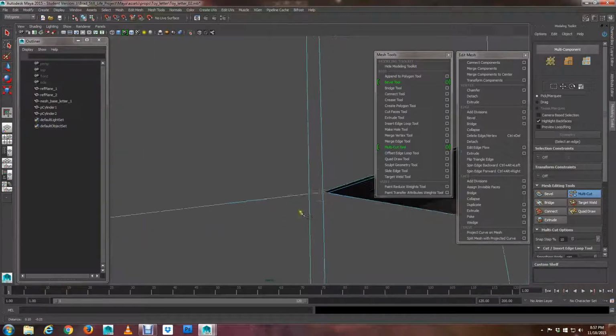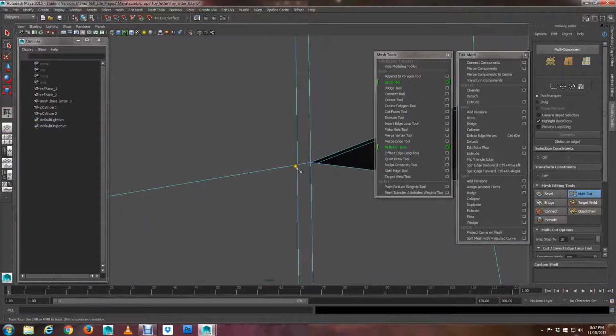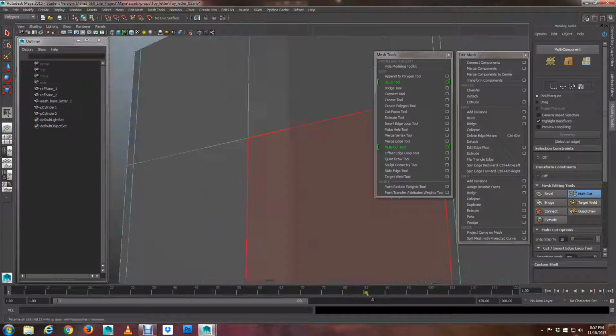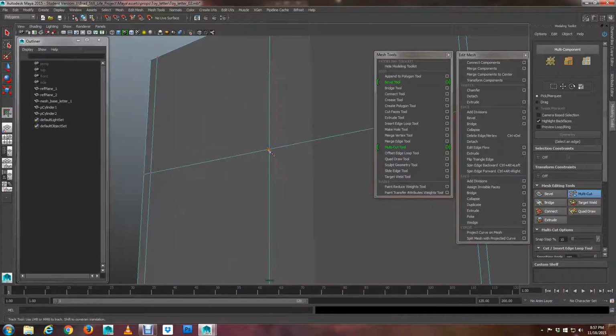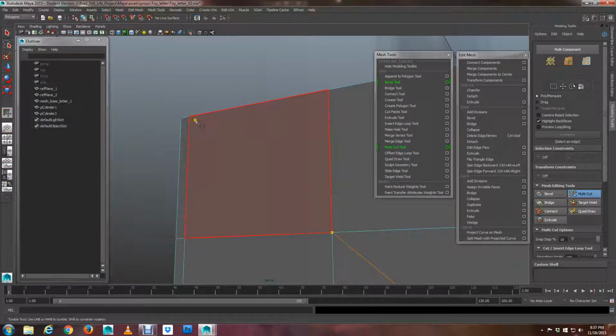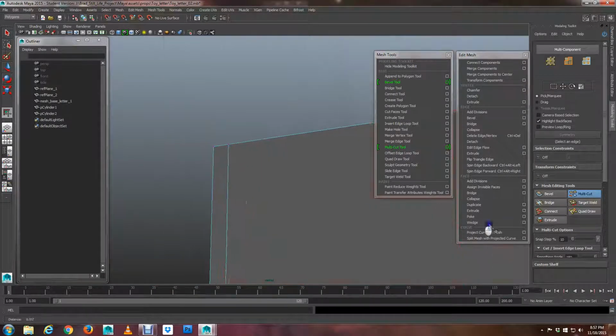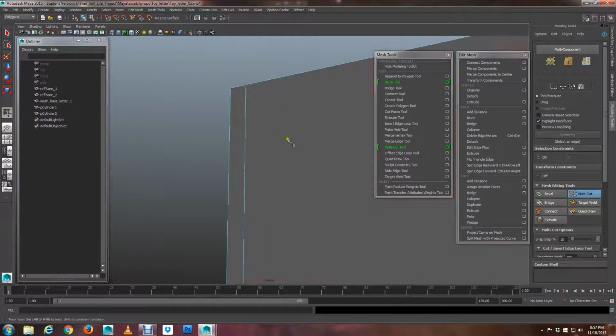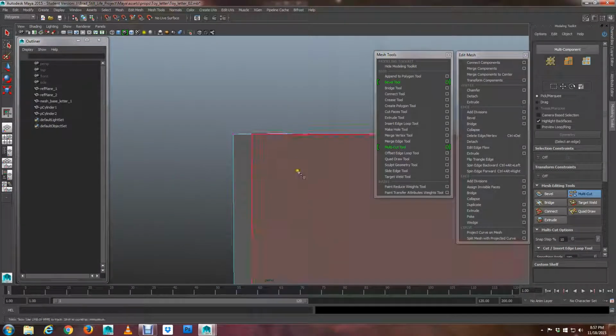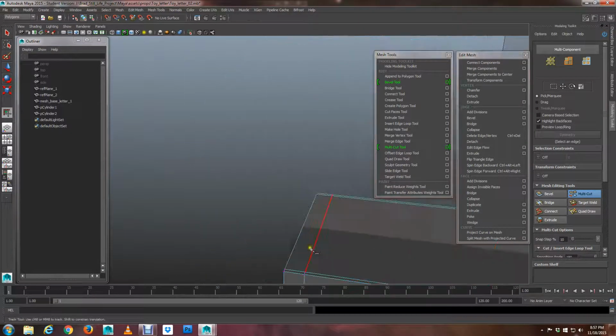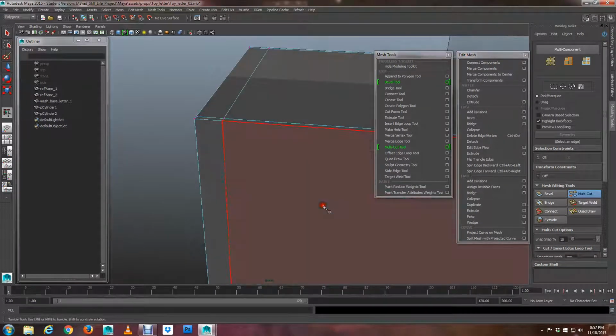And again, when you're making your cuts, zoom in to a point. Okay, so I got this point until it goes red. I click there. I'll zoom out a bit, come up here. That vertex goes red, so I can click there. I know I need to make a cut up here, but I'm going to zoom in and rotate around a bit until I can see this point.